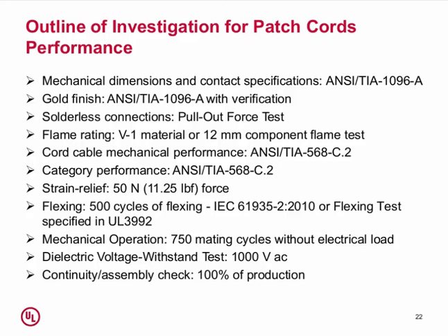If you look at how they approach the requirements for connectors and how these connectors are used in low voltage circuits, V1 material will be appropriate. So we really just adapted it from those specifications, because that's the most common use for patch cords, is with IT and communications equipment. From a cord cable mechanical performance standpoint, we rely on TIA 568-C2.